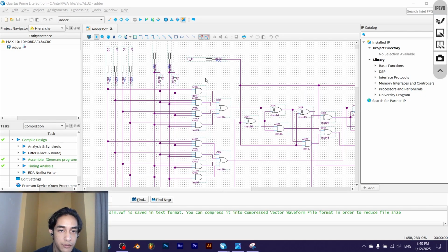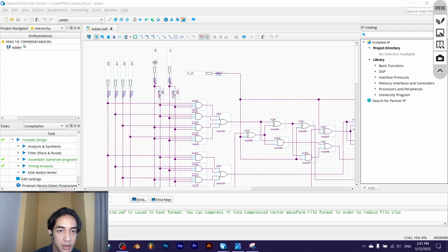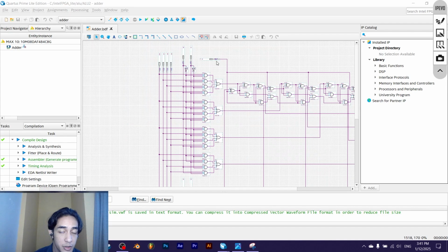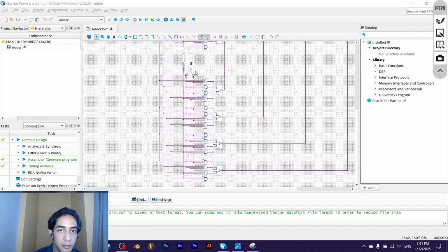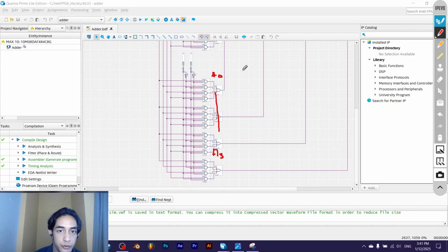As you can see, the multiplexer are made of 4 AND gates connected to one OR gate, and for selector it uses NOT gate for the complements of the selector input. For A multiplexer, it has 4 of these sets. So from the top we have A0 until A3. Same goes to B multiplexer. It has another 4 of these sets to produce B0 until B3.